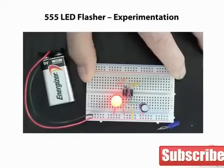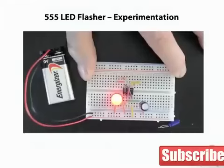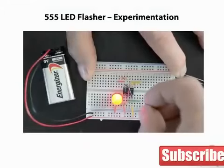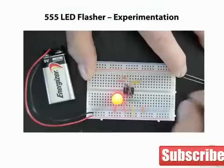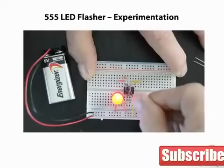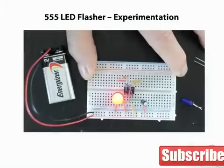We would expect a very slow flash rate. Trying again with the 1 microfarad capacitor. Quick flash rate. And back to our design capacitor of 10 microfarads. Roughly a flash rate of 1.4 cycles per second.